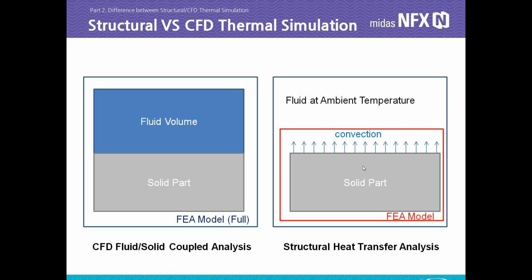condition. And then you have CFD, fluid-solid coupled analysis. In this type of analysis, you are modeling the solid as well as the fluid volume. So you are modeling everything, and you don't need to add this convection condition between the solid and the fluid, because this will be calculated automatically by the software.